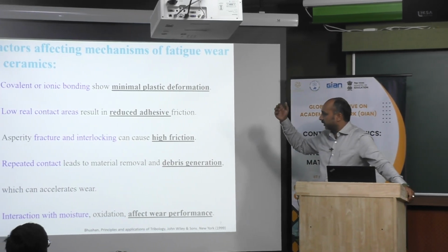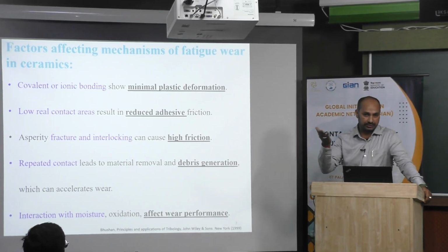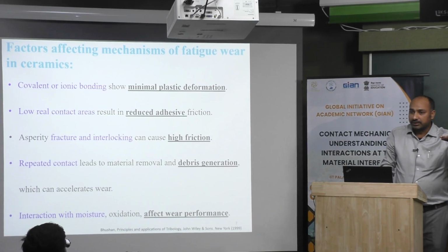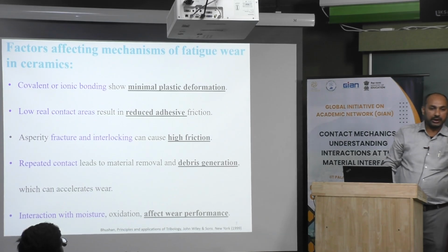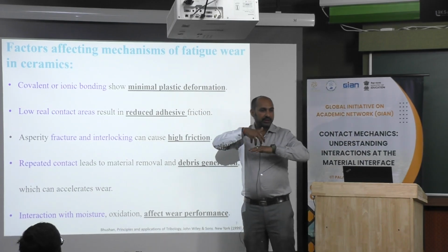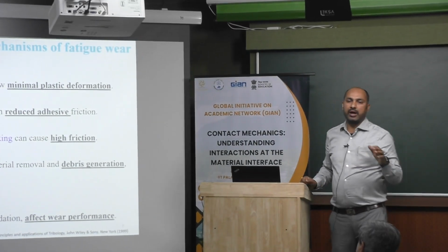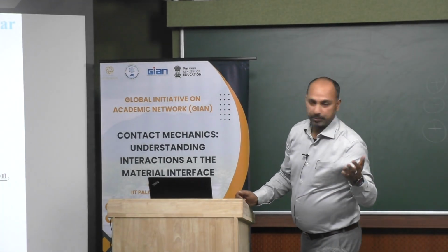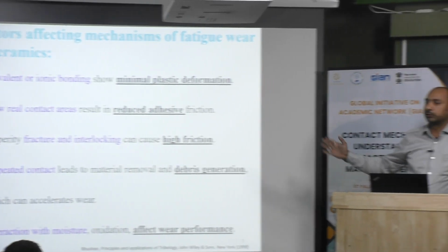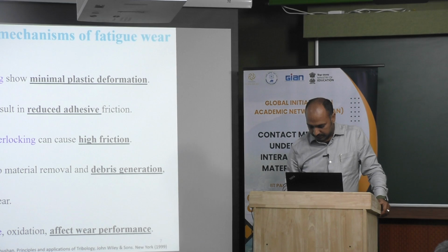Then asperity fracture and interlocking might lead to high friction conditions, because they are hard enough. Just now Professor Mayank has shown that they have high friction if you go for hard coating, but at the same time low wear. Because they are hard, wear is less, but they get interlocked, so friction will be more. Friction could be higher, but if your requirement is to reduce wear, we can go for ceramic coating as well. Then the interaction between moisture and other things also affects ceramics very drastically, so I will cover that here.